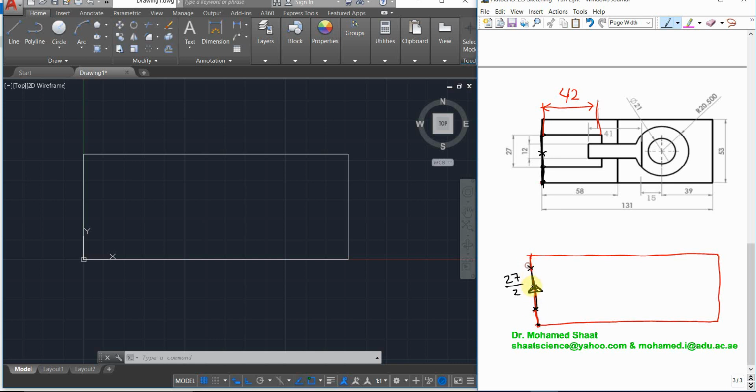But you have to remember that we already drew 2 lines here, right? These 2 lines that you drew, we have to remove them. As we mentioned before, I drew these 2 lines just to assist me to locate a point. But these 2 lines are not physically existing in the drawing. There was an original line, which is the big long vertical line, already there. So if you just keep these other 2 lines that you drew to locate these 2 points, this is gonna give problems and errors when we try to convert the shape into 3-dimensional modeling in the next steps, right?